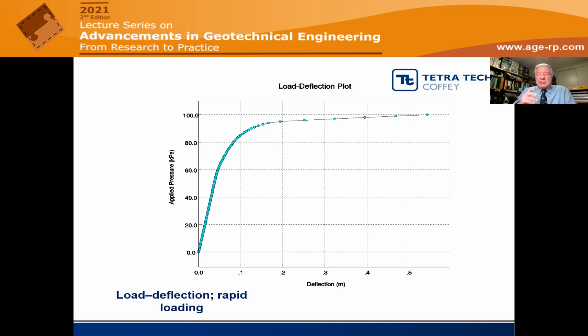And so this, I guess, just verifies what we had known from basic bearing capacity theory, that under loading conditions where we have rapid loading, the rapid loading case will be the critical case, and the long-term case, if we can put the load on very slowly and allow dissipation to occur, then the loads that we can sustain are going to be significantly greater than those which we could sustain with very rapid loading.